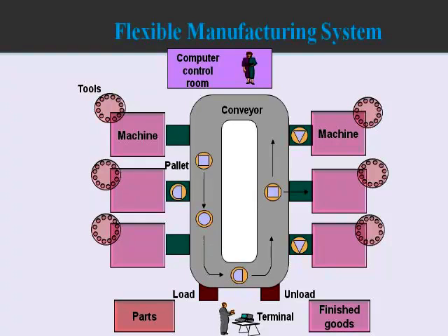Once the machine is processing the program, the tool selection and the tool life, how much is the remaining tool life of that particular tool, they're all automatically recorded, and in the automatic tool library maintained by the controller, all this data is appended. So we'll come to know what is the remaining life of the tool on each machine.